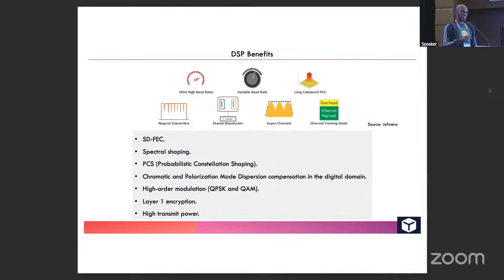And that soft decision FEC, even though it consumes additional bits in the payload, you go from about, let's say, 15% with hard FEC to about 37% with soft FEC. You essentially improve what's known as the net coding gain, the NCG. You can improve as much as 12 to 15 dB with SD-FEC, which can translate to thousands more kilometers or significantly more bandwidth. And that's always the goal, to get as far and with as much capacity as you can.